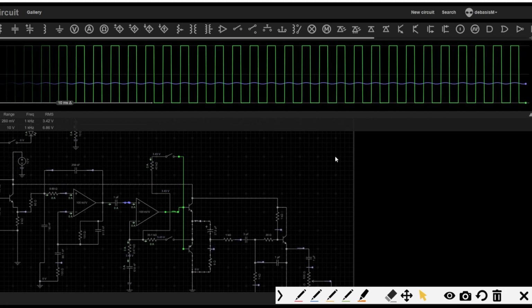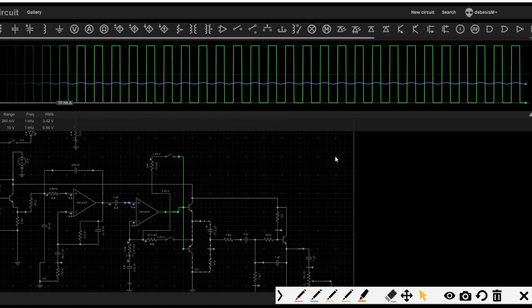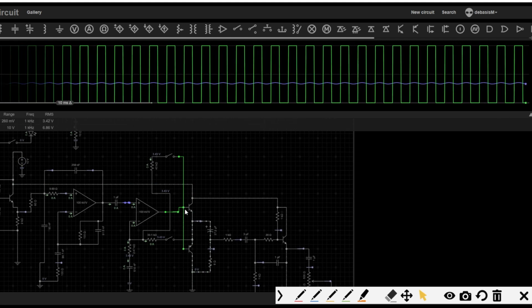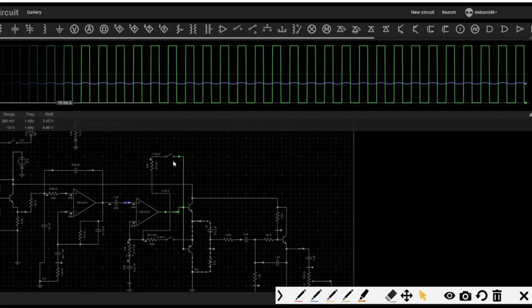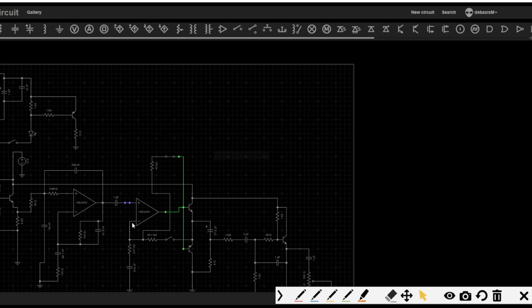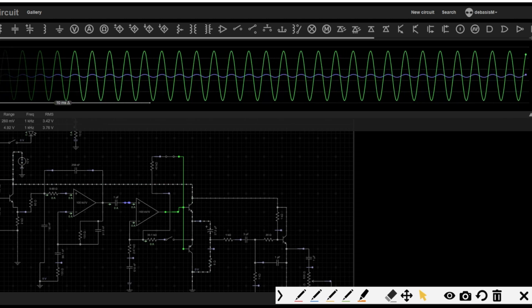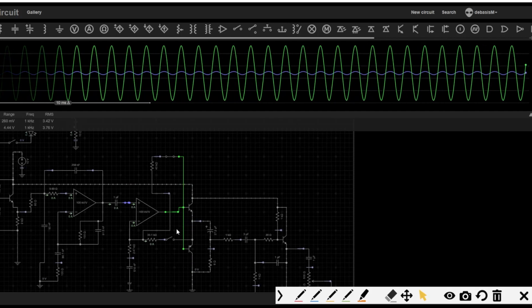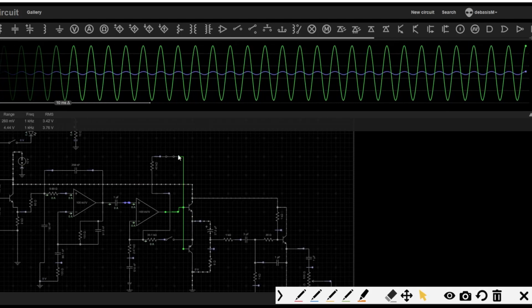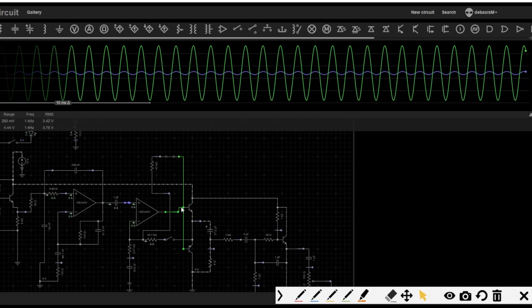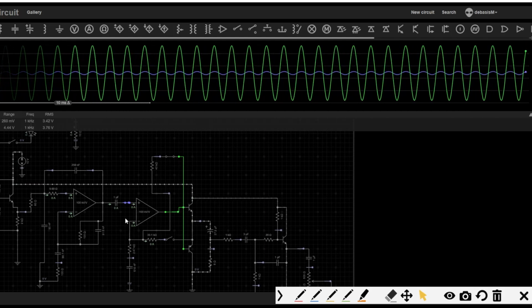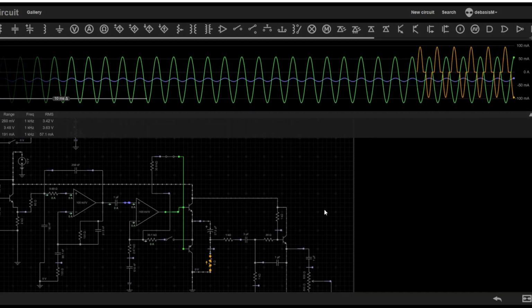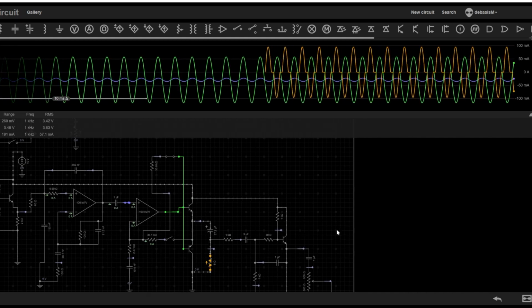So in a classic class B audio amplifier, what is done is you give a feedback loop from the base of this dual transistor through a resistor to the inverting point. See here, that feedback is tracking this voltage. Once this switch is closed, that base voltage works as feedback to the op amp. This is the interesting thing that I wanted to show you.